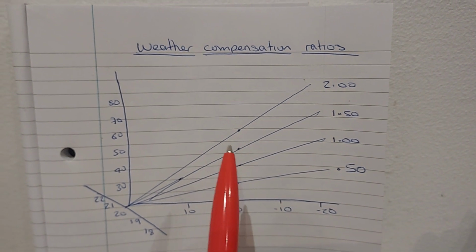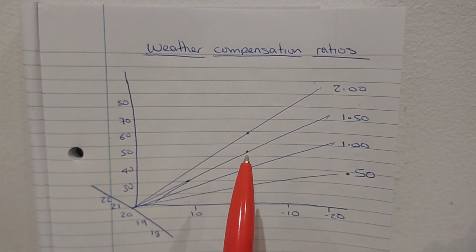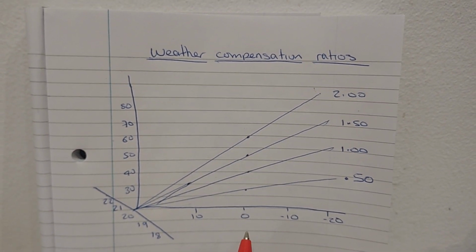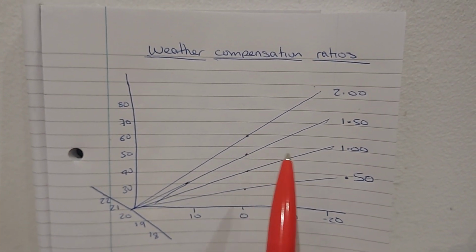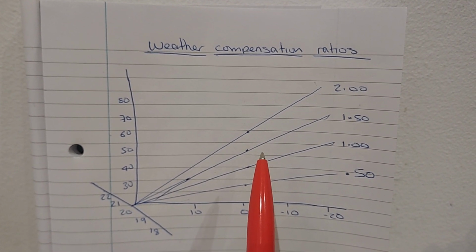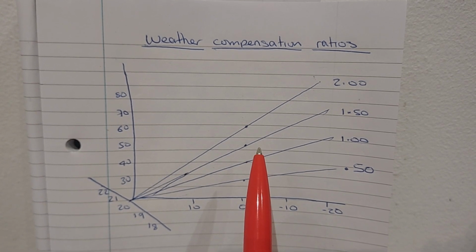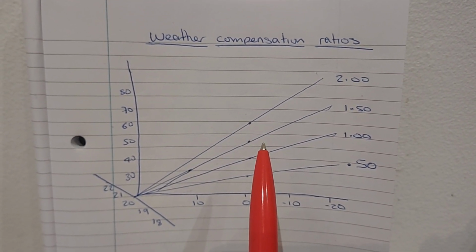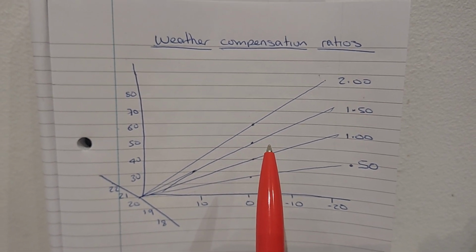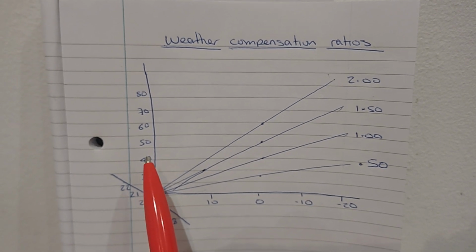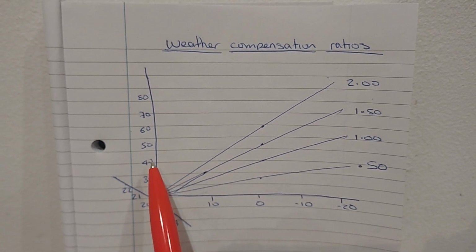So if you're designing for 50-30 on a gas boiler, so you design for a 50-degree flow temperature, you'd be looking up here, down here, and you would probably come to a curve of 1.4, which coincidentally is the curve we set on nearly every Wiesmann we install, which tells us that nearly every radiator installed in the London area is already running a 50-30 design for a gas boiler, which means a mean water temperature of 40.